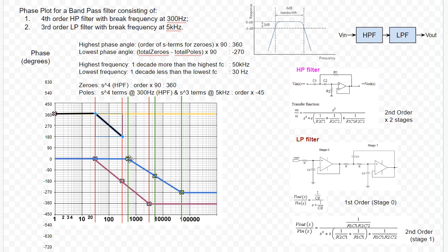All right, so then there's another break frequency here. That means between 300 to 500 hertz, is there a difference? Let me see. Well, actually, there's no difference. So in fact, this line will continue because in this range it's 0 degree per decade, 0 degree per decade. This is still 180, so that means that 180 will just continue on until it reaches this frequency.